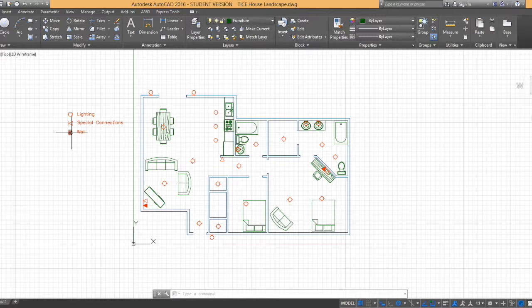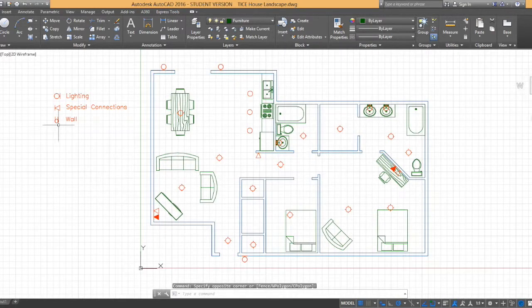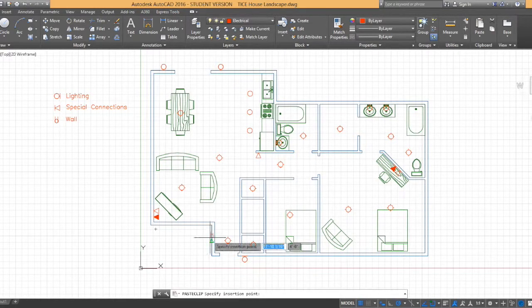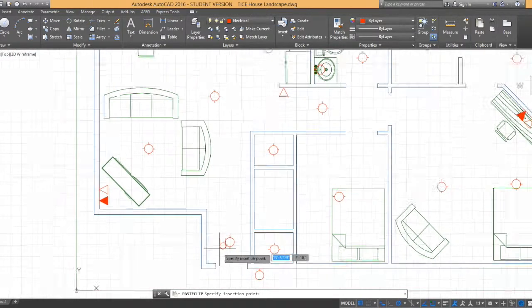Residential building code states that for electrical outlets, no point of the wall along the floor shall be more than 6 feet from a receptacle. What this means for us is that outlets should be placed within 6 feet of an opening or a door, and then along the wall no more than 12 feet apart from one another.